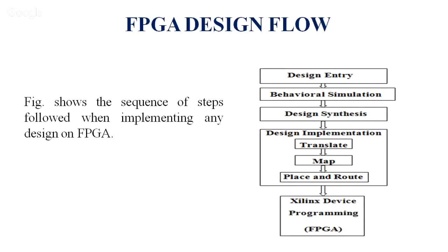So without discussing much more detail about FPGA, I am going to show how we work on FPGA. For the very basics, first of all, if we want to work on any tool, we need to write a program. This is the flowchart by which we can burn our logic on FPGA. First is design entry, then behavior simulation, design synthesis, design implementation, and then burning our program on the Xilinx device. I will explain these blocks one by one.